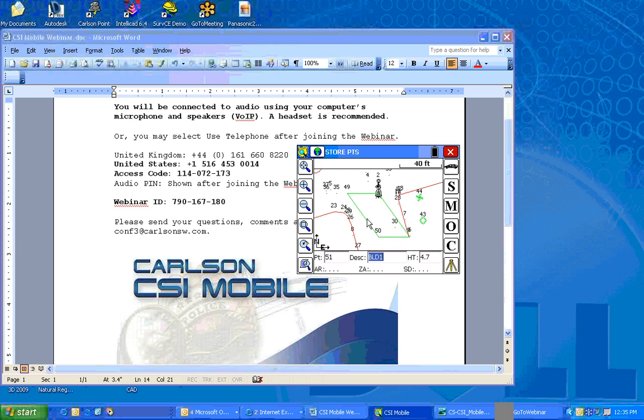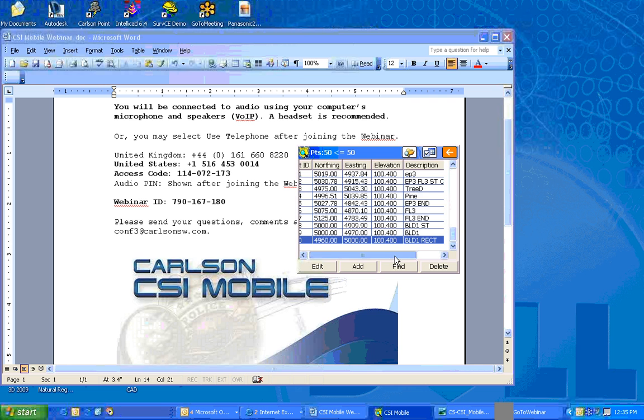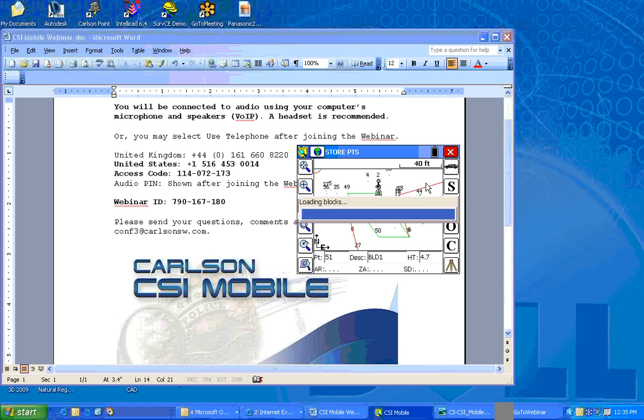Now, if you wanted to, say it was shaped like this, there's two ways you could have made this a building. You could have gone in the code, go over to points. You could have gone BLD space rect and then done space OH, at the very beginning, OH like 0.1 and OV10 for a 10-foot vertical building. But another way is do it after the fact.